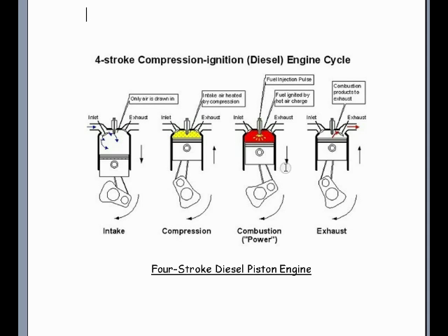The maximum rated brake horsepower and torque are reached at very minimum RPM due to the fact that the pressure on the piston head is so much greater than with a gasoline piston engine. Pressure times piston head area is equal to dynamic force, so the force on the piston is much greater in the diesel than compared to the gasoline.